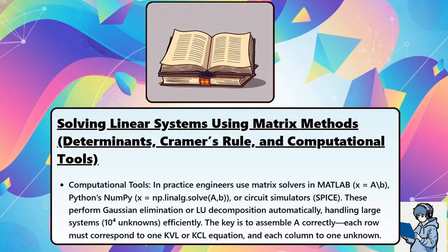Computational tools. In practice, engineers use matrix solvers in MATLAB, x equals A\b, Python's NumPy, x equals np.linalg.solve of A comma b, or circuit simulators, SPICE. These perform Gaussian elimination or LU decomposition automatically, handling large systems, 10 to the 4th unknowns, efficiently. The key is to assemble it correctly. Each row must correspond to one KVL or KCL equation and each column to one unknown.